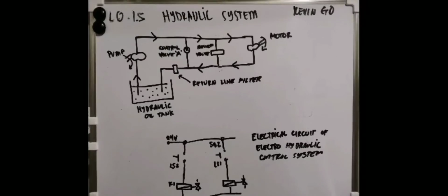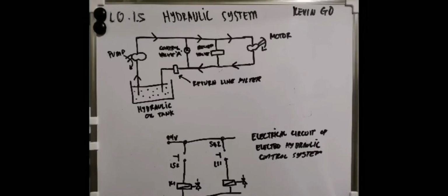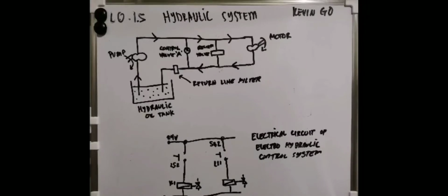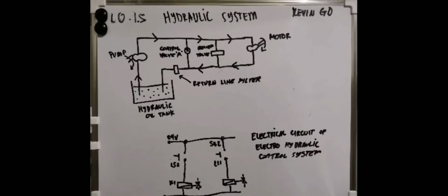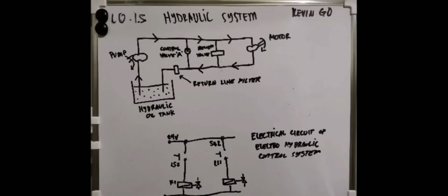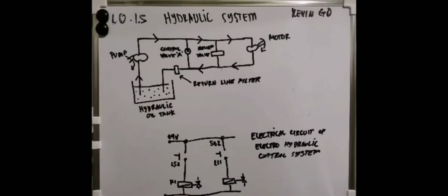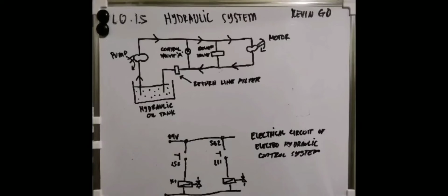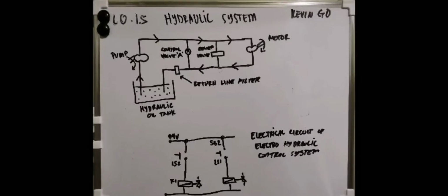Five main categories of equipment to achieve this power transmission in a hydraulic system are: the hydraulic pump to convert mechanical into hydraulic energy, valves to allow this hydraulic energy to be controlled, hydraulic cylinders to convert the hydraulic energy into linear force and motion, or hydraulic motors to convert the hydraulic energy into continuous rotary motion. Ancillary equipment including filters, heat exchangers, tanks, pipes, etc.